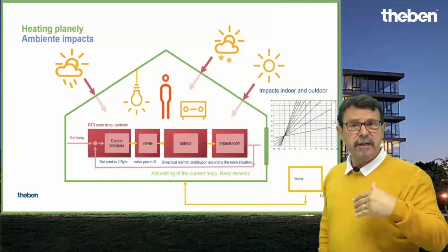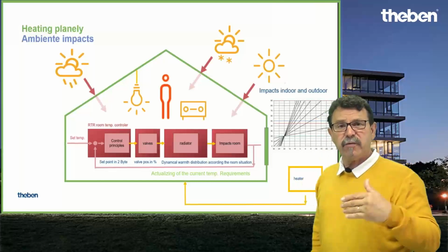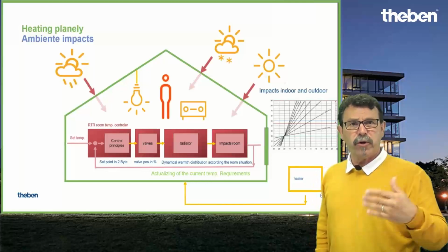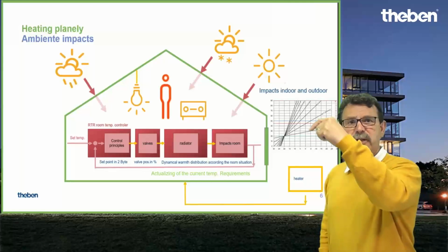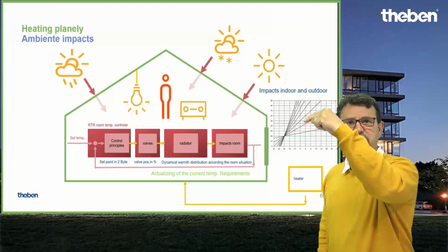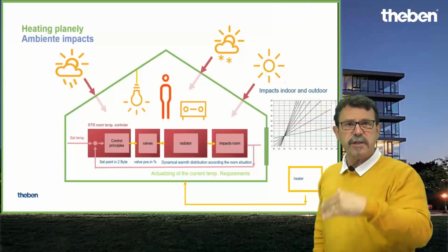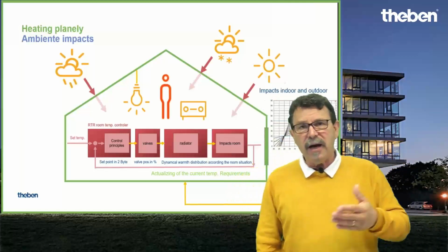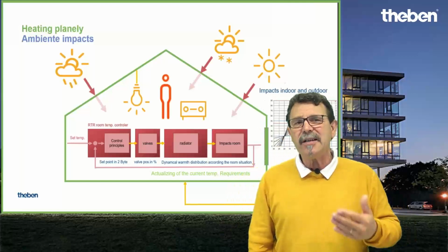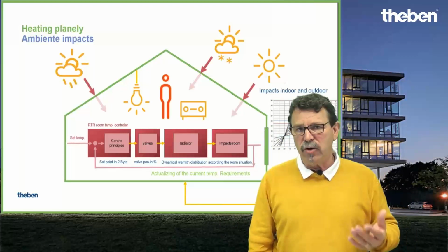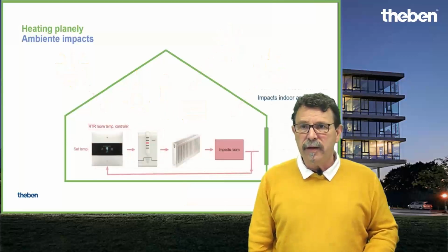If the heating actuator gives feedback that currently all channels, all heating circuits require a lot of warmth, we can shift automatically with this heating gateway, we can shift this heating curve 1 or 2 degrees up. And so we do have the required warmth in the room. So automatic adaptation, highest degree of energy efficiency and highest degree of comfort for you.